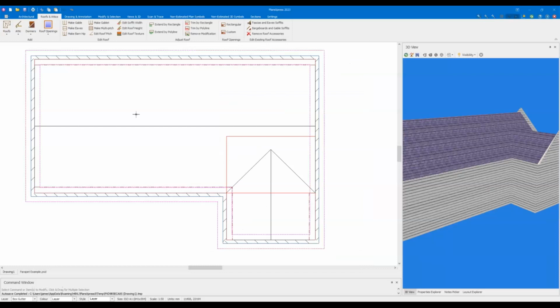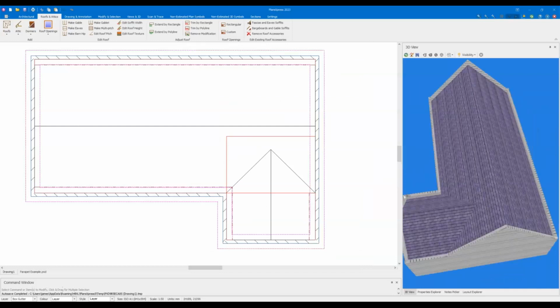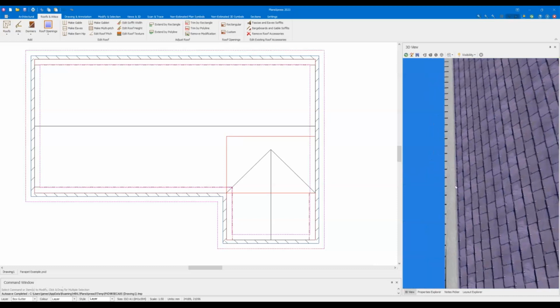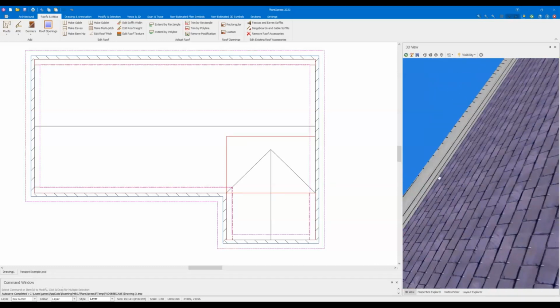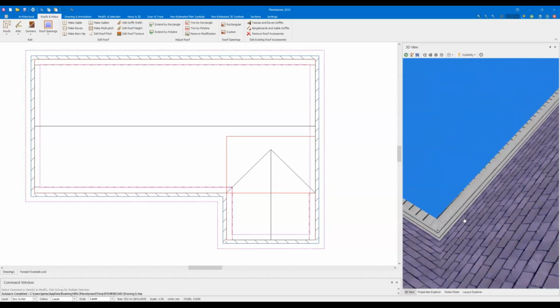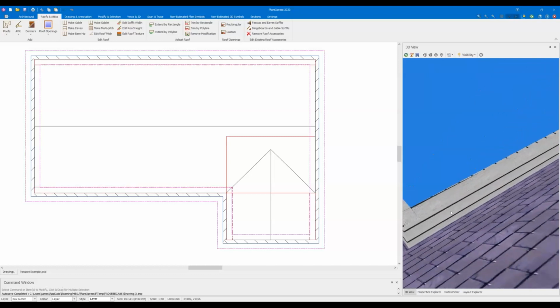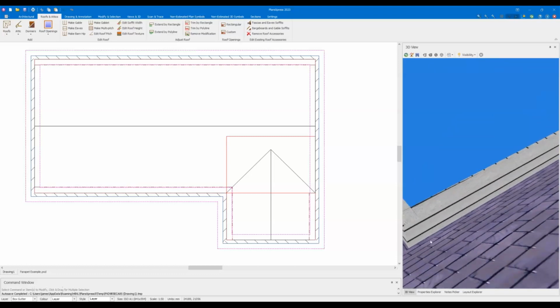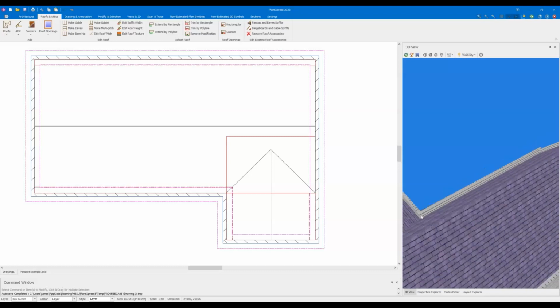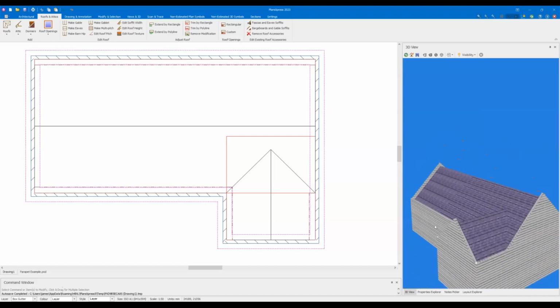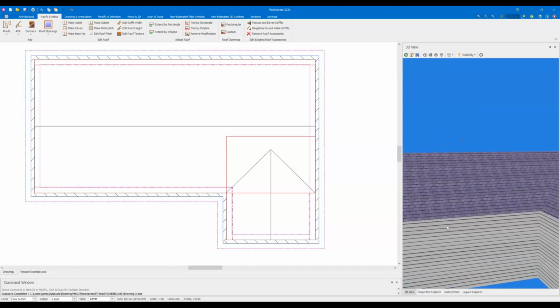So we've got our walls in, and I'll just briefly show you if I zoom in. The 300mm that we set for the height of parapet is this internal dimension. So it's the height from the top of the tiles to the top of the parapet, to the bottom of the parapet capping, I should say. So that's the height that we set and has been drawn.